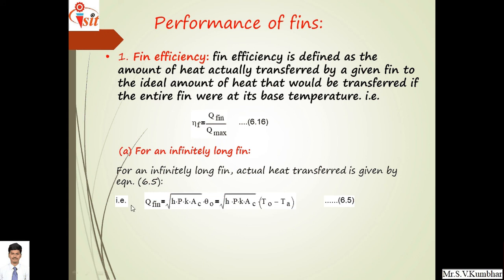Now we have already derived this equation. For an infinitely long fin, actual heat transferred is given as Q fin is equal to square root of hPkAc into (T0 minus Ta), where T0 is the base temperature, Ta is the ambient temperature. This is the replacement for theta 0.